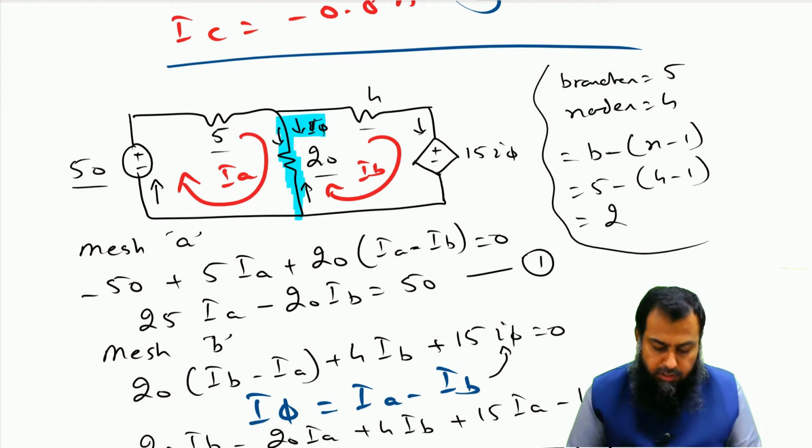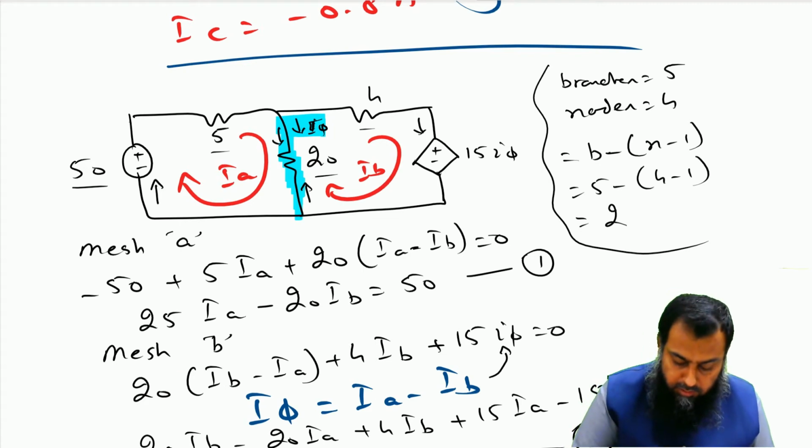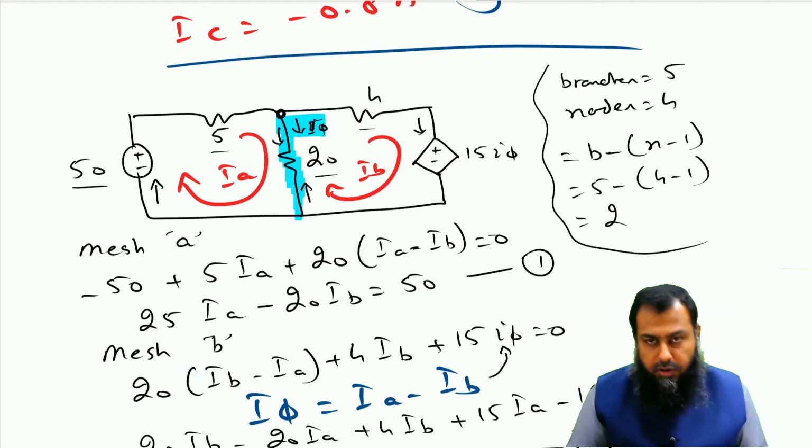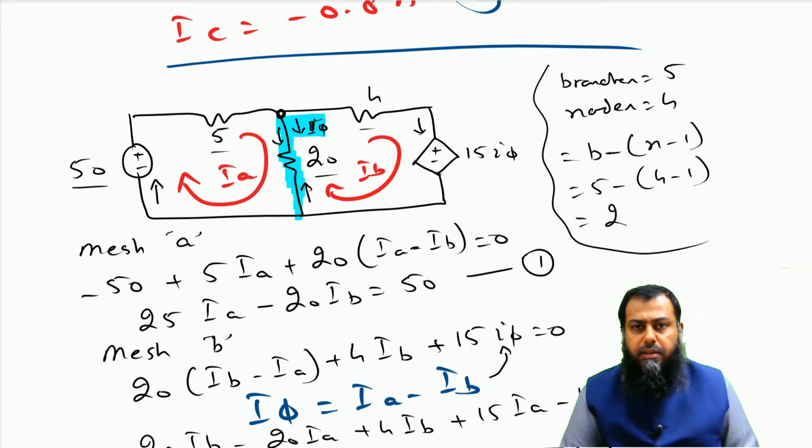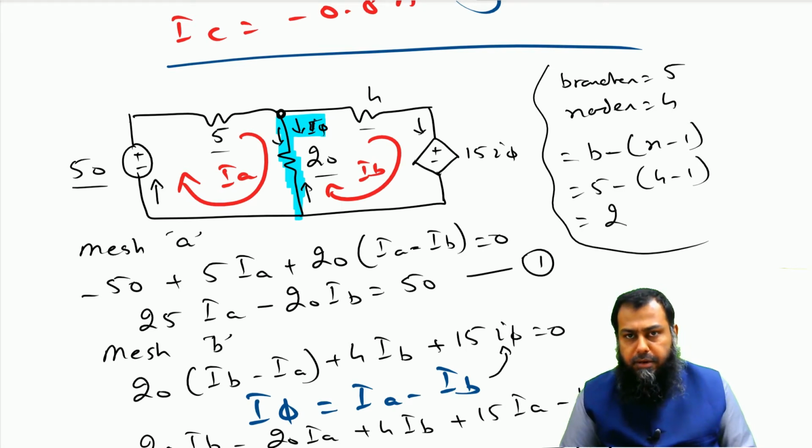You can then apply Kirchhoff's current law on this particular node, and thereafter you can also apply Kirchhoff's voltage law to verify whether your answer is correct or not. You can further examine this by computing the total power consumed and delivered by each of these elements, and thereafter you can see if Tellegen's theorem is validated for this particular circuit or not.